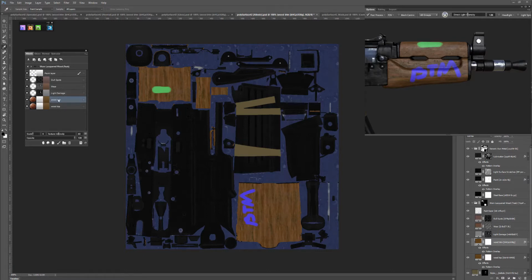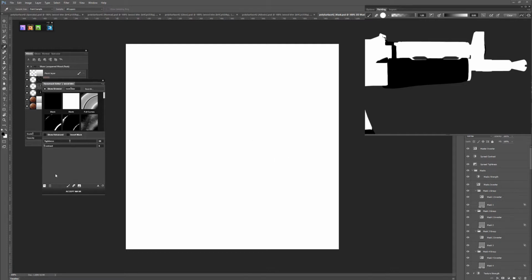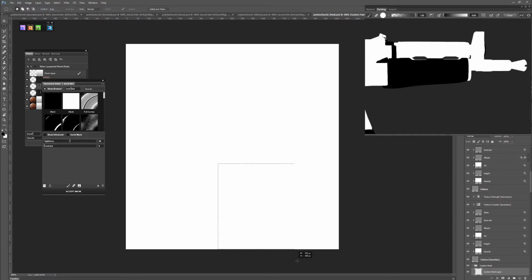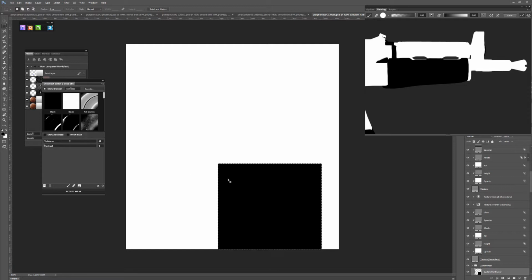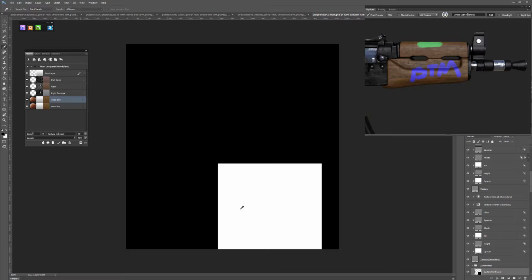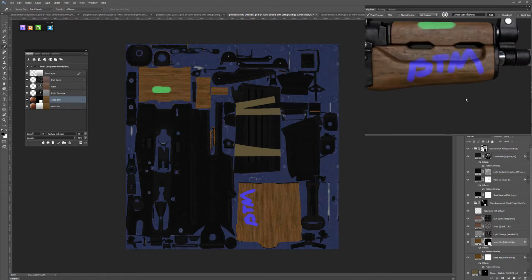So what we really want to do is click on the Edit Dyna Mask, and we'll go into Quick Painting mode, which is just a black and white version, so it's a little bit faster to work with. And inside of here, we want to click on Paint a Mask in Photoshop. So I can use any tools in here, and I know it's about this section here, so I'll just paint that. Well, actually I want to invert this mask. So click on the Invert button and accept this mask. And that's going to get the results and also update over here in my panel so it will recognize that it's changed. So now let's force this to refresh in our 3D view and take a look at this.